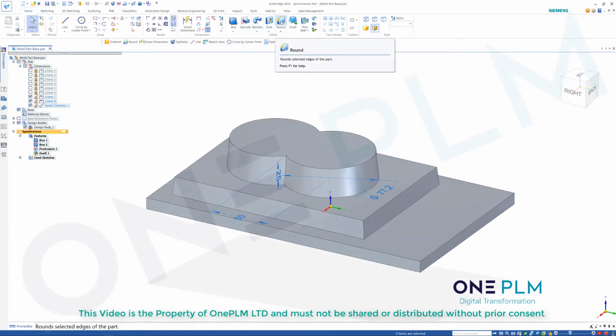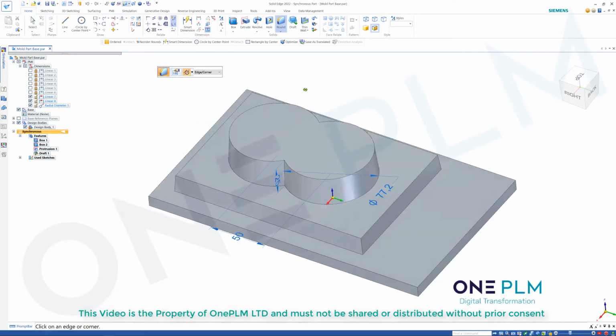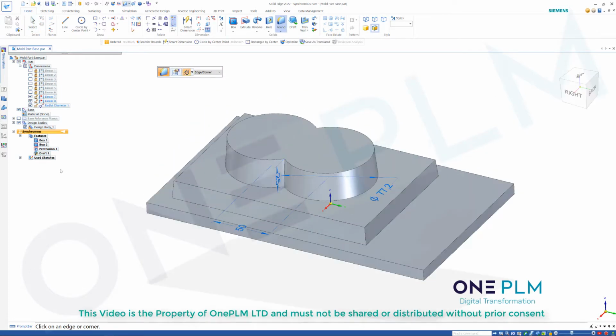So let's do some rounds on here. When we do rounds in synchronous, I tend to do them all nice and separately. Notice this little box where we've got these options. If I press C for chain, F for face, E for edge, we can use those keyboard shortcuts, which can make stuff a lot better. So I'm going to do the face, and I'm going to go 3mm.